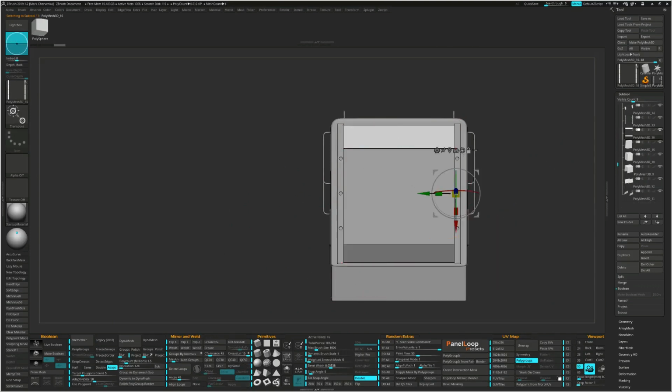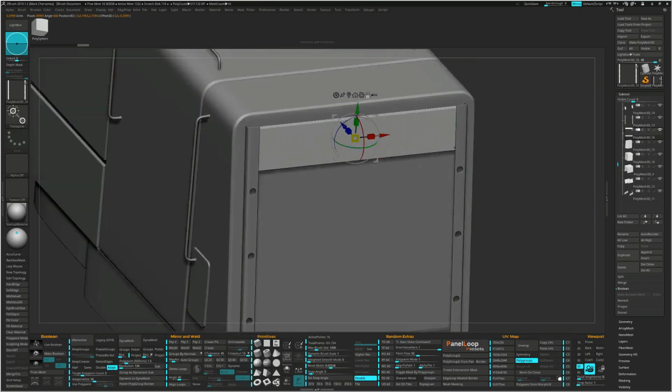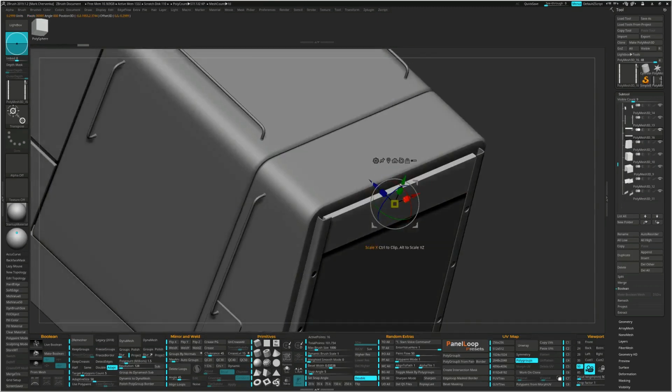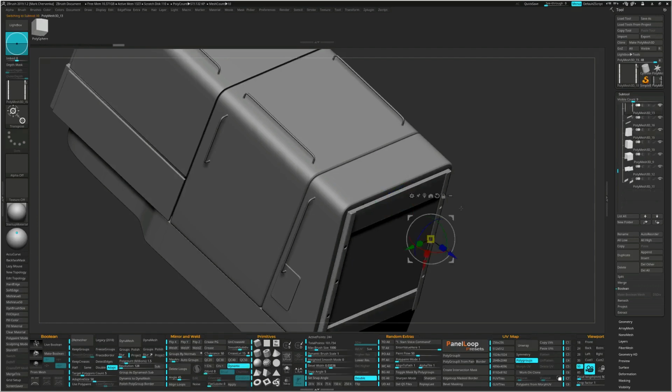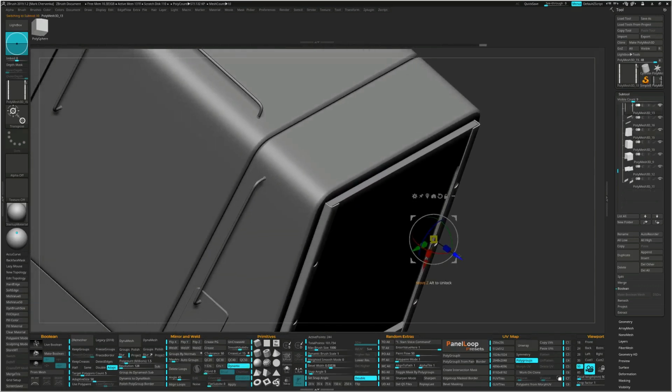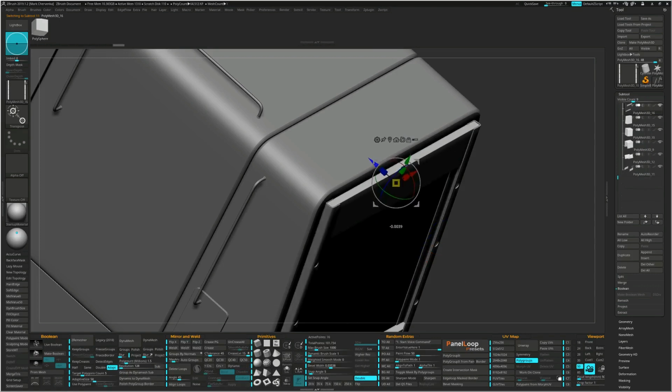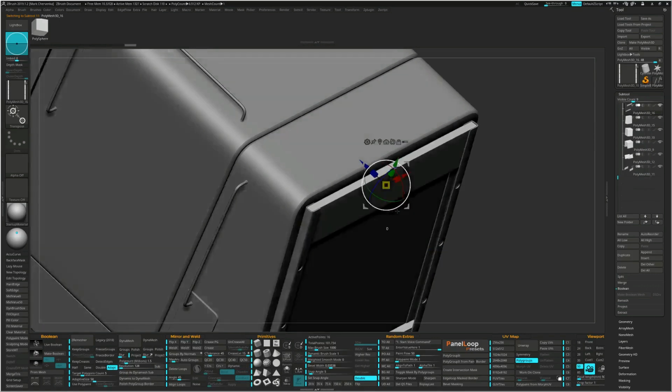This model will have a lot of dynamic subdivisions and Q grids, which can be deceiving for the poly count. It may say 1 million polys, but when you send it to KeyShot with the bridge, ZBrush will apply all those dynamic subdivisions to real subdivisions. So you may have to go back and lower dynamic smooth divisions or the Q grids before sending.